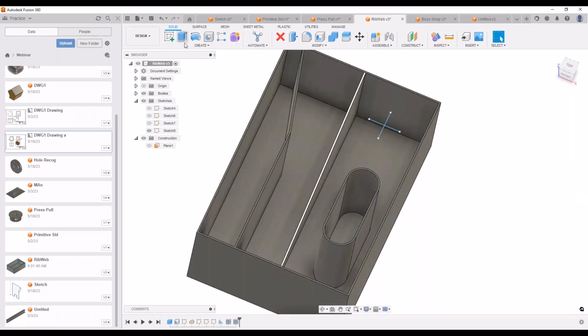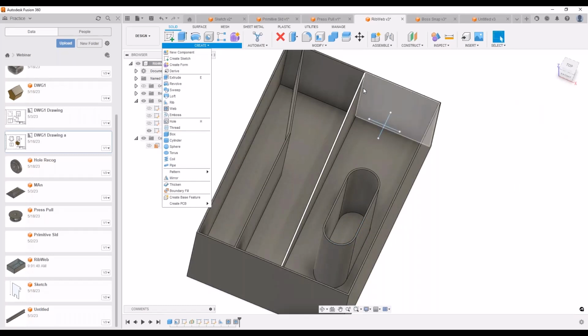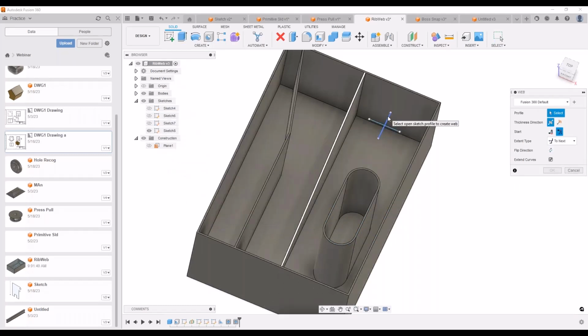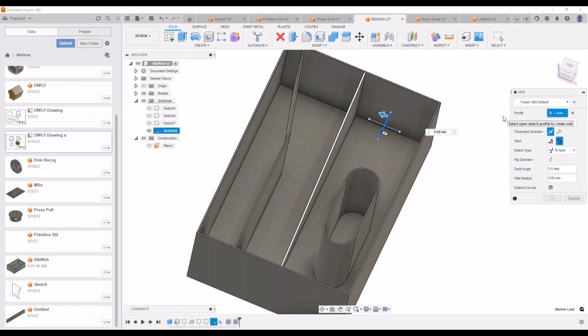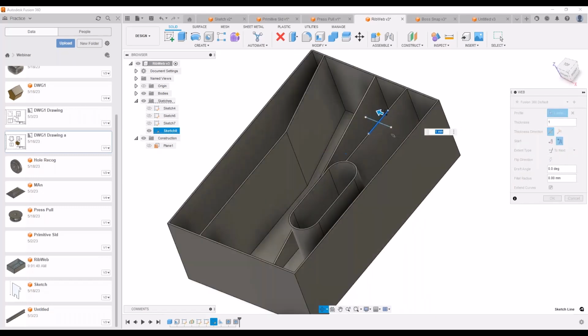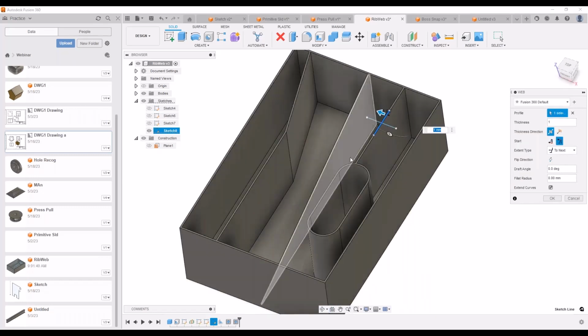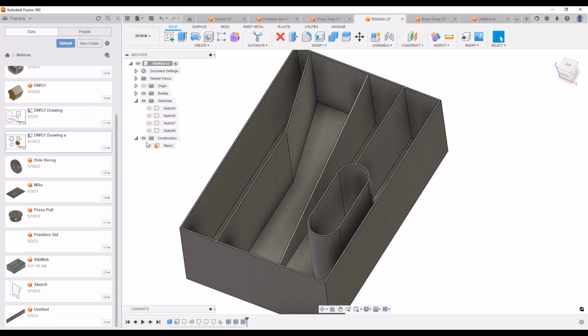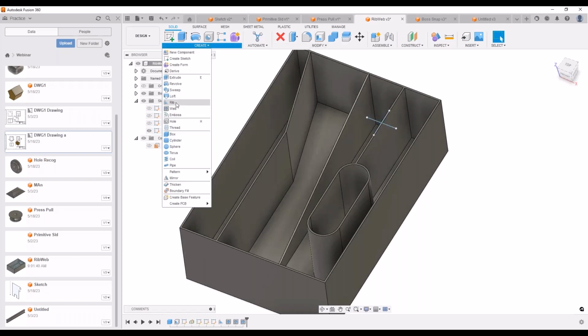Interestingly, you'll also notice that I've created a small short little crossover there. What it does is when you click on web there and you then specify the thickness again, see that it actually takes it along that line up to the next nearest features. However, you'll also notice that once you've used it, the sketch is consumed. So let's actually open up the sketch again or make it visible again.